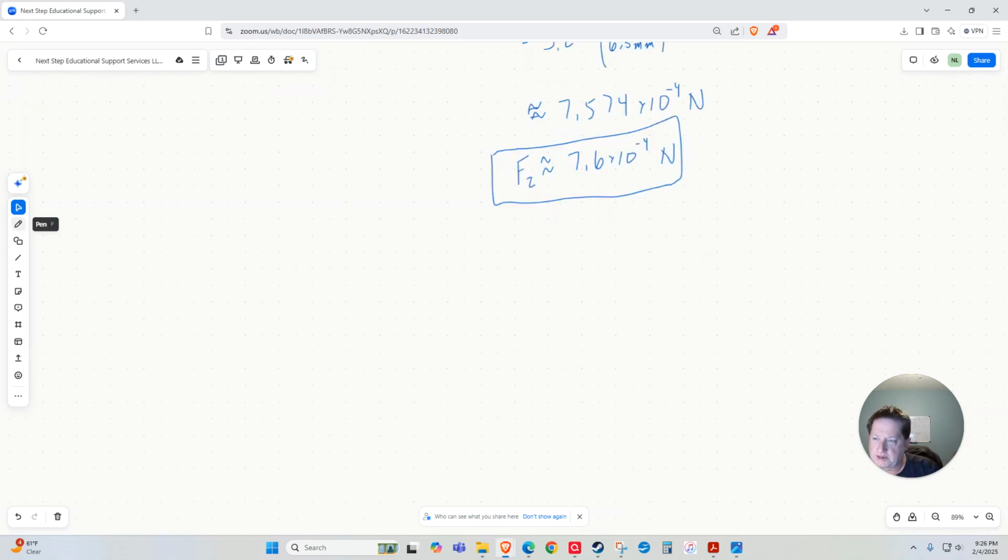Okay, so we're starting with the same basic initial setup where the pressure on the plunger is going to equal the pressure at the needle. We're resetting the subscripts 3 and 4 here since it's a slightly different scenario. Again, another difference here is we actually have the pressure here, so we don't need to replace that with force per unit area. But we do need to replace pressure 3 with force per unit area because we don't know the pressure there without calculating it.